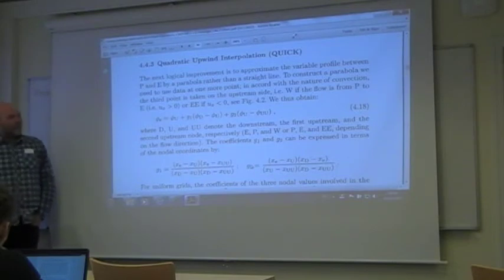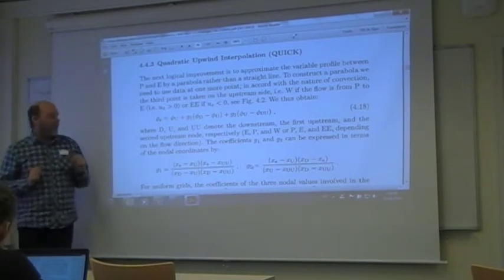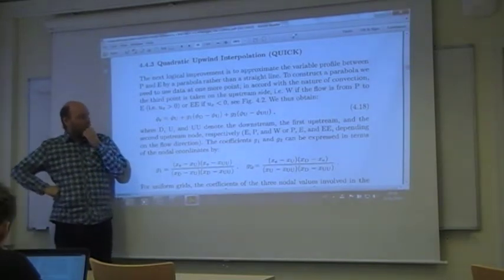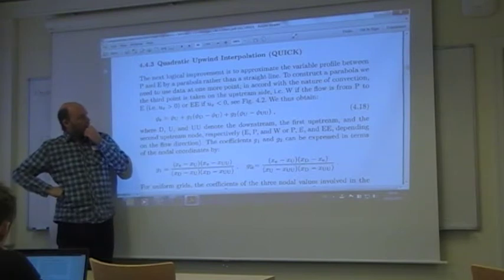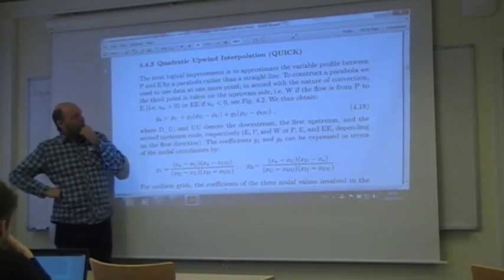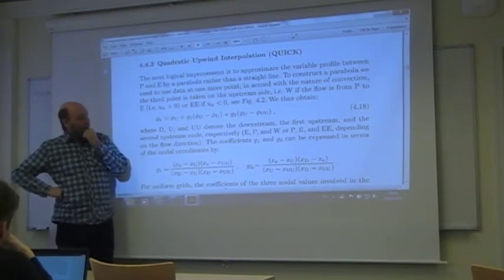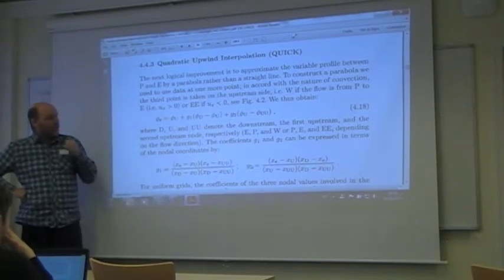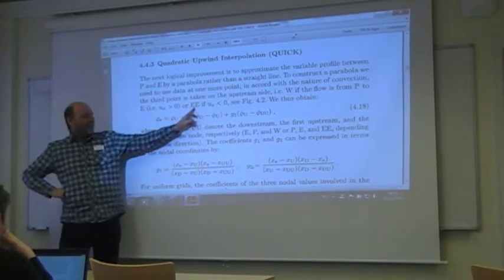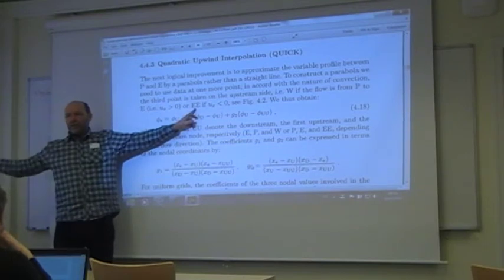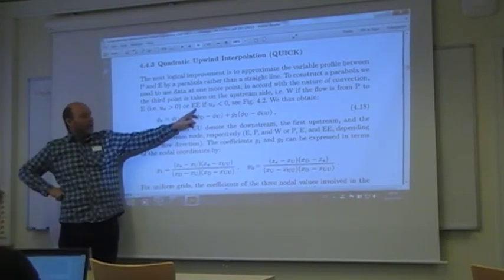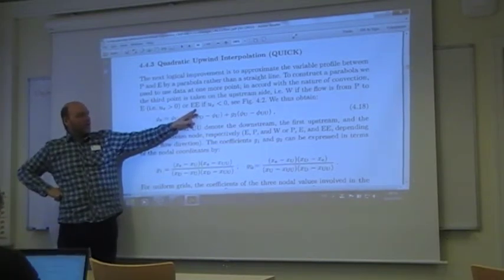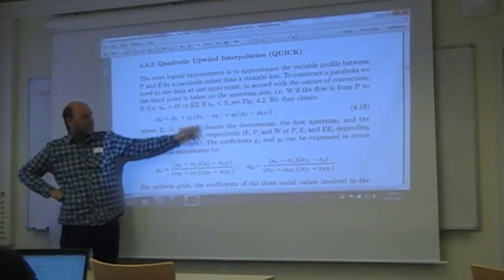You use some additional points outside just the two that we have done so far to create one single derivative. So doing this, using a quadratic upwind interpolation scheme, you have to go even one additional neighbor upwind. So not just to the east, but also to the far east as well.